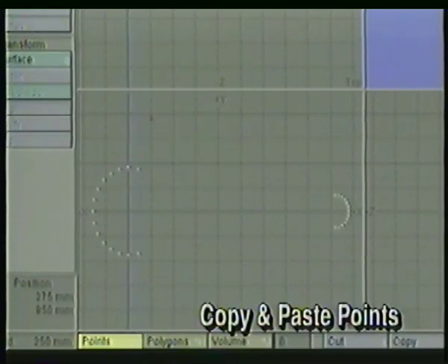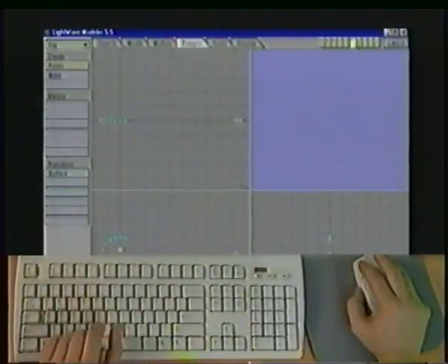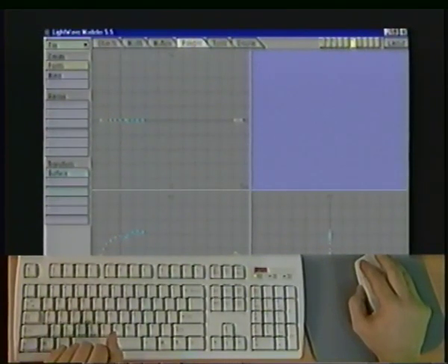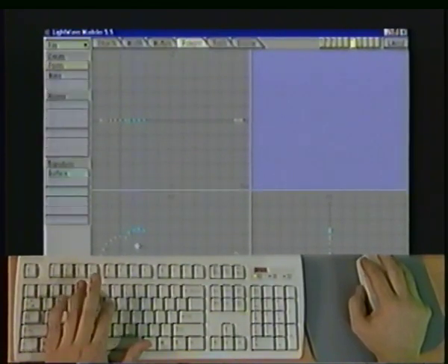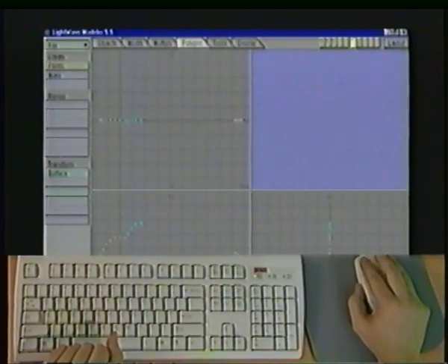I'm going to add a few more points right here for that funny little spike that sticks out. And you notice the spike was slightly curved. So what I'm going to do is steal some of these points, copy them, paste them, and once again hit T on the keyboard to go to move, and I'm going to drag these points up, and now I'm going to hit Y on the keyboard for rotate, and rotate these up into position,